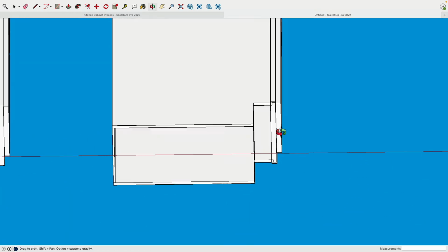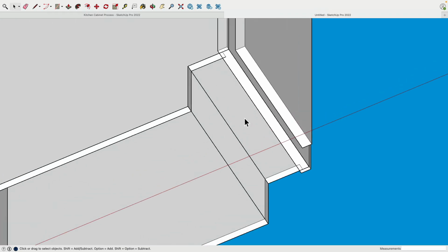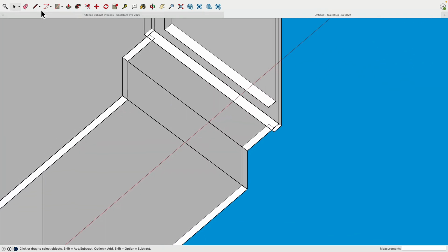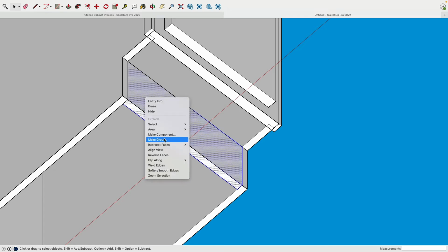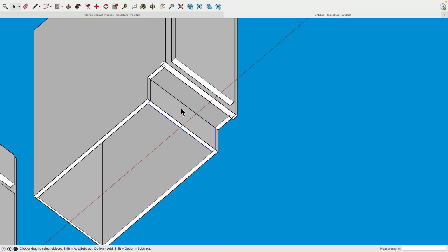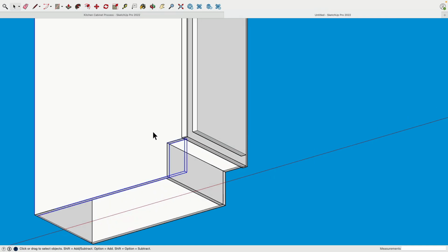Pretty nice. So let's take a look at the bottom. Here we need a fill. We can do this 0.5, 1/2 of an inch, a little bit thicker. That's our foot area. If we tap against it, we don't want this to break. The back is against the wall. That can be thinner. So that's all good. This here I will hide right now.